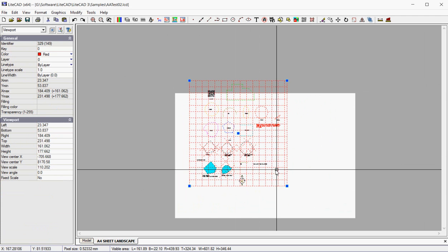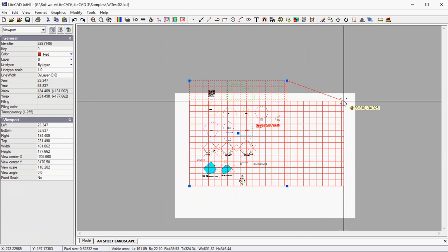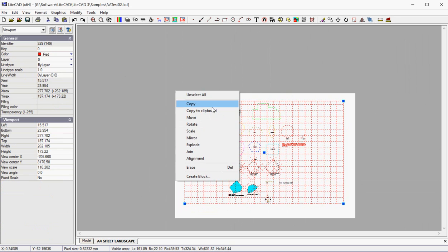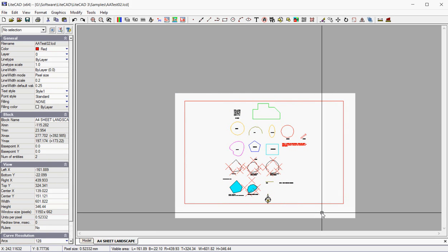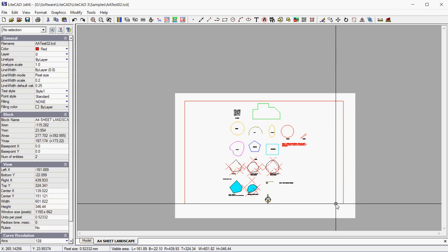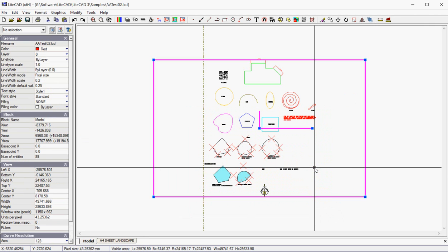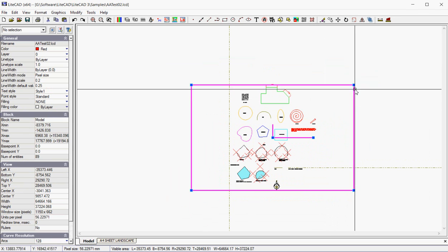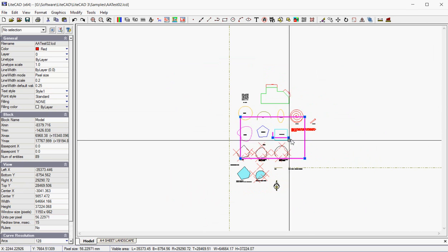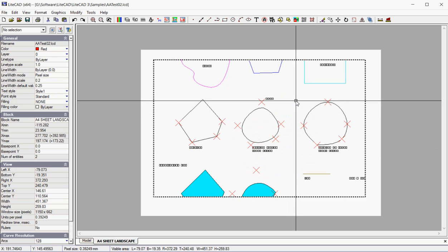But this zone that you see here is called a floating viewport, and it's quite flexible. We can use it in this way to size it, and I'll unselect by right clicking and picking unselect all. This now represents an A4 sheet, and I can put a logo on the bottom right hand corner. This floating viewport, if we select it and click inside it, we get back to the design. So I can change the size of the space. Let's zoom in a little and position this magenta box, and then we'll right click and display on the layout. And you see we've changed.